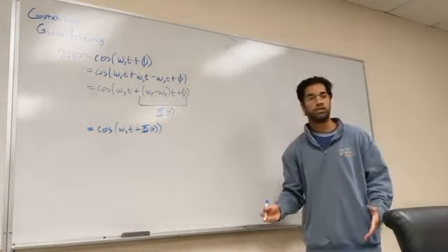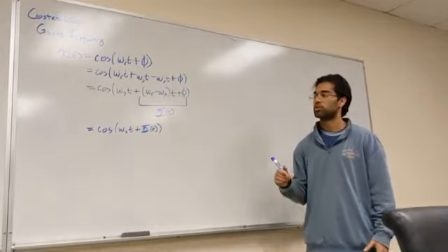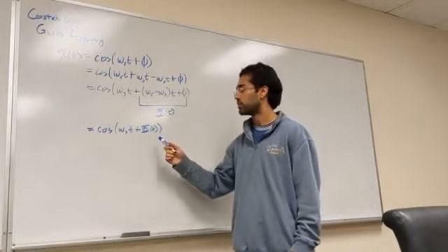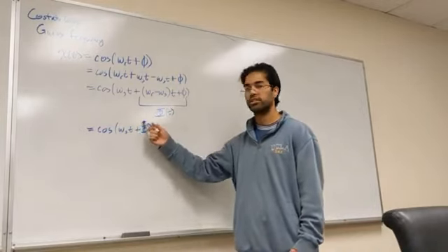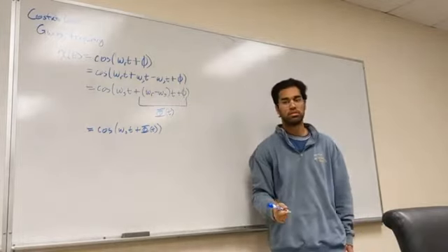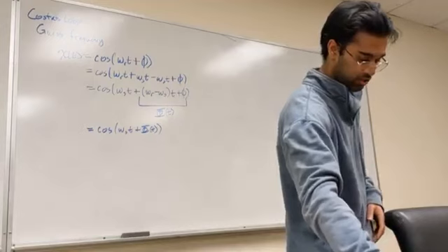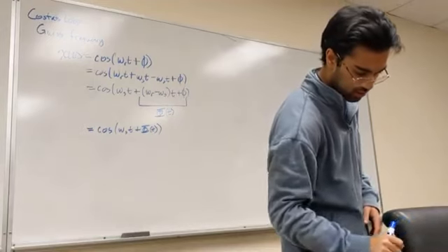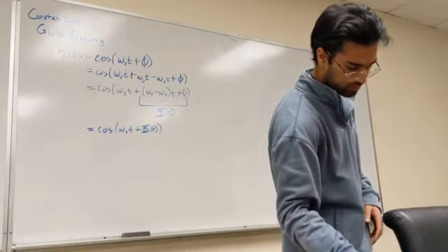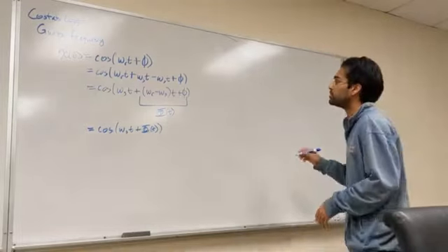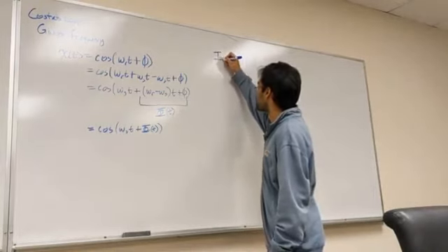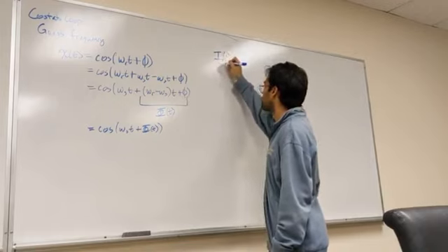So what the Costas loop does is try to create a phase offset, which we'll see later, to match this phase offset. Because we already know this, omega s times t, we're going to try and match it. And I'll try and show you guys that in a second. So when we come to demodulation, we have our received signal, or received information.